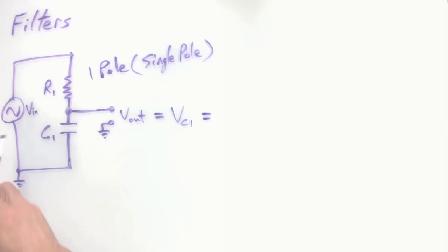If you remember all the way back to the DC course, basics of voltage division, if it was two resistors, of course, the voltage divides up according to the resistance in the circuit. Then when we moved on to the AC course, we had to adjust our thinking to a more universal thought, that impedance is really the way to go with AC involved and reactive components. So basically, this voltage here at the input is going to divide up with this voltage divider according to impedance.